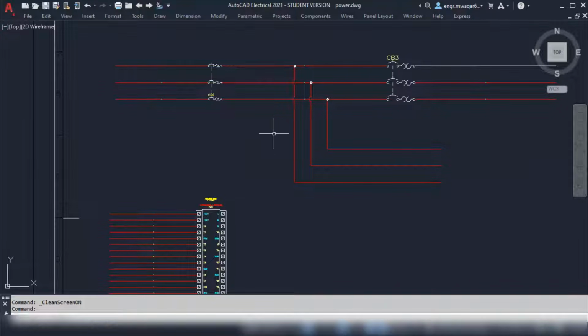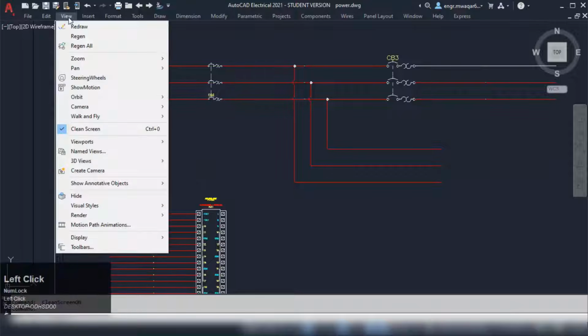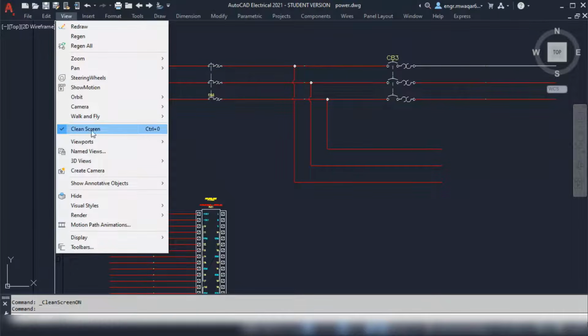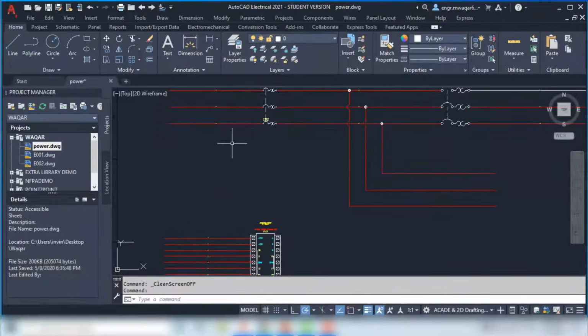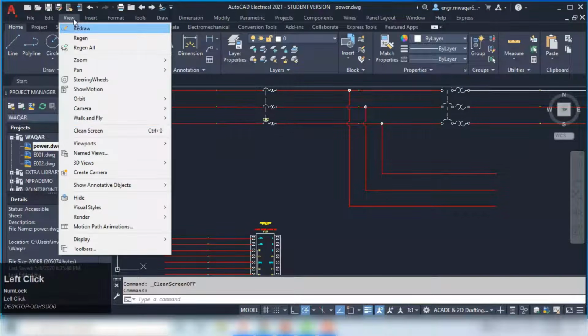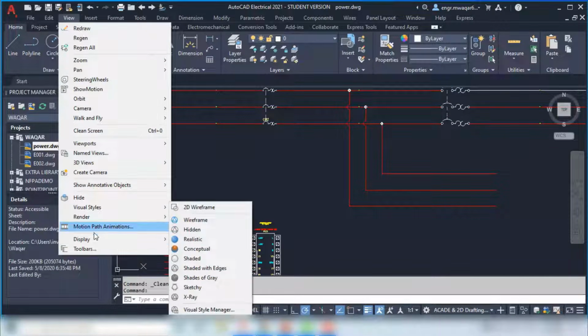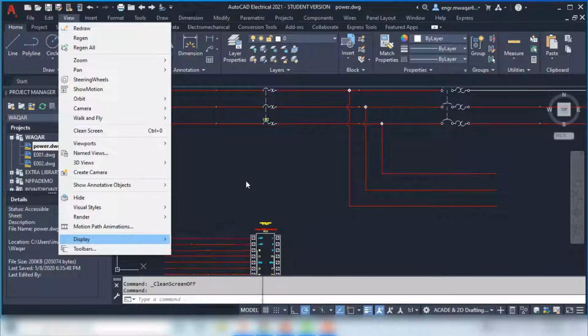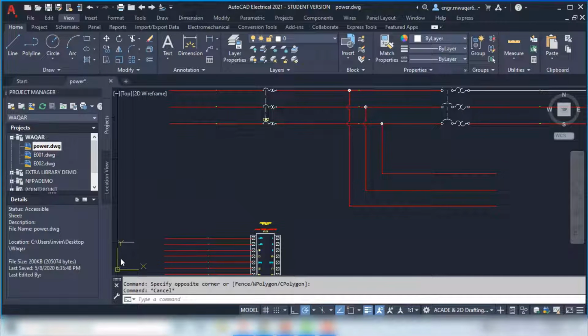That's the trick I wish I'd known 5 years ago. It's amazing how much screen real estate we waste on the ribbon when we're just doing fine detail work. It's pure productivity. The second trick is just knowing you can toggle the visibility of every other element, the UCS icon, the view cube. Turn off what you don't need.